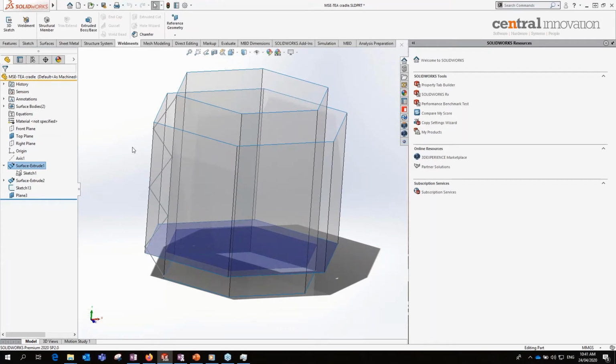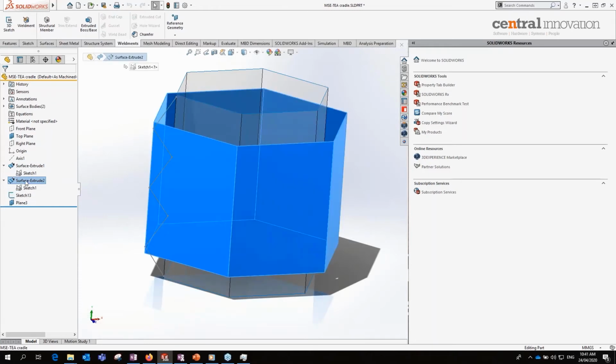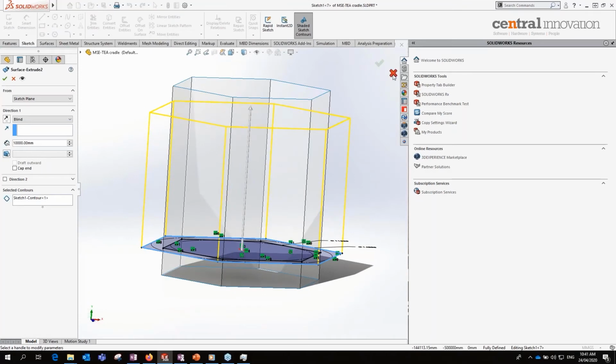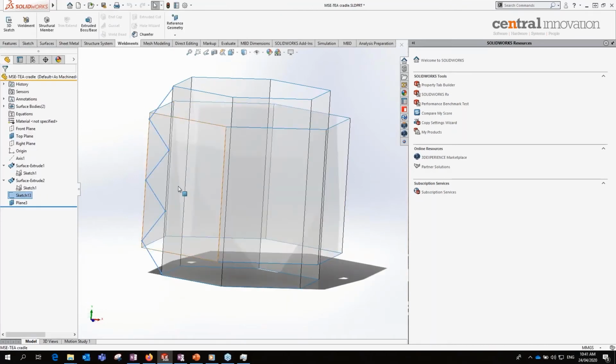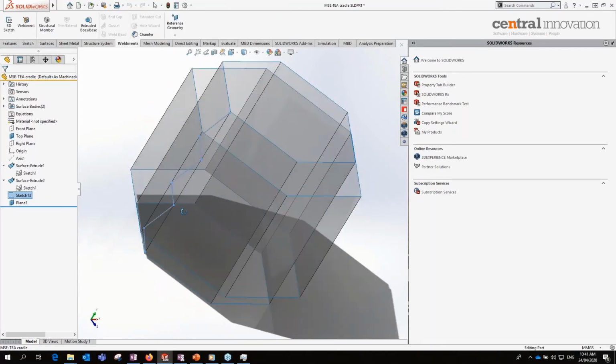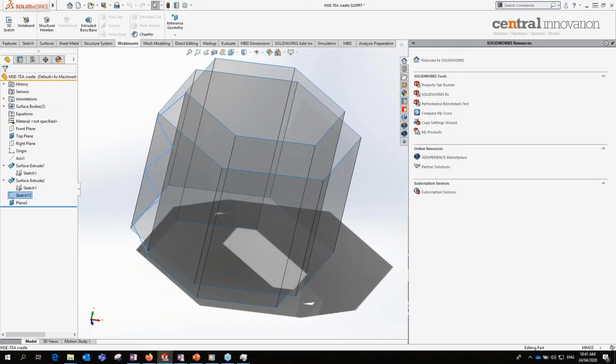It's almost a zero thickness sheet which has no weight. We use it as a supportive tool to create a solid body or for any hybrid modeling techniques. So we create here surfaces, and now the outer surface as well, which is a little bit shorter than the other one, and a sketch for the secondary members that will connect them together. Yep.